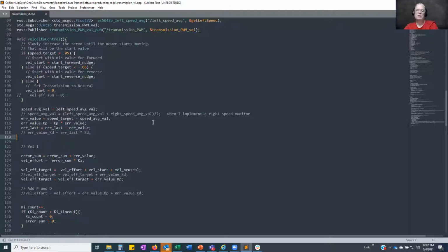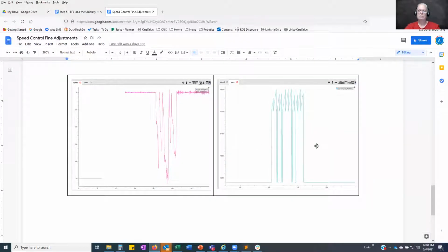No, I agree that you have to get your speed correct before you add any of the navigation stuff on top. And same thing with the steering, you got to get to the point where you can give it a command velocity message and have the thing actually do that. One point on those graphs you were showing, instead of running your actual control code, just put out a PWM that's about 50% speed.